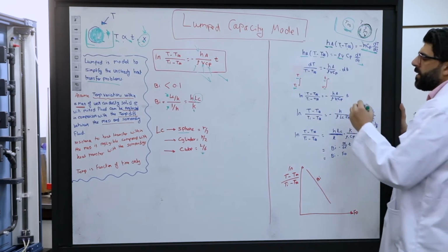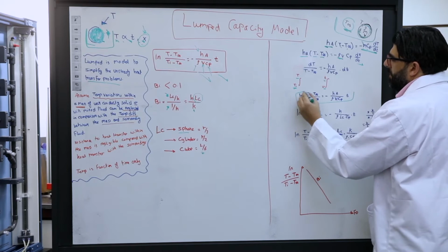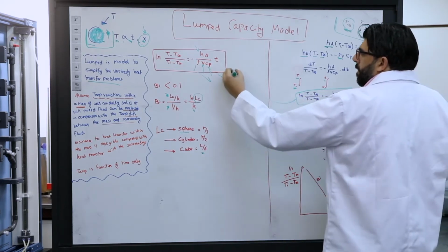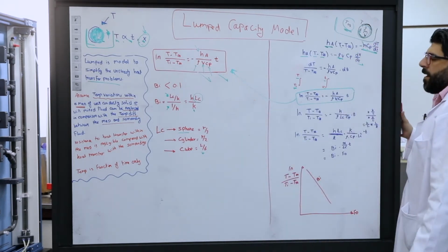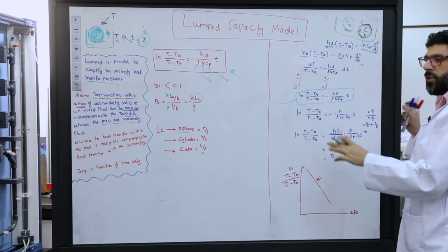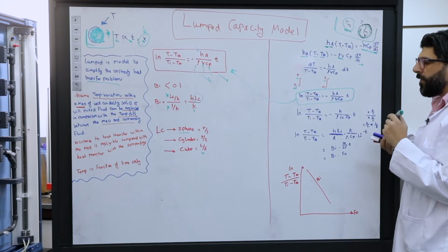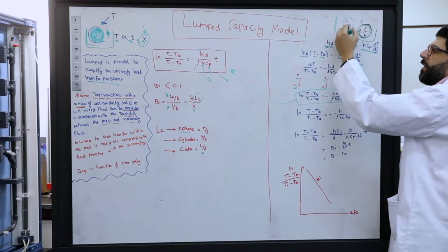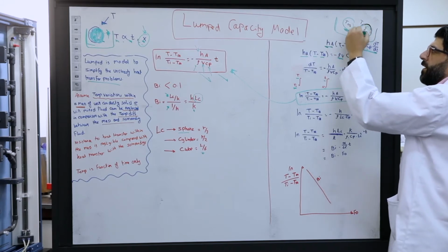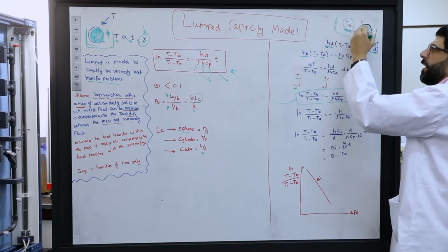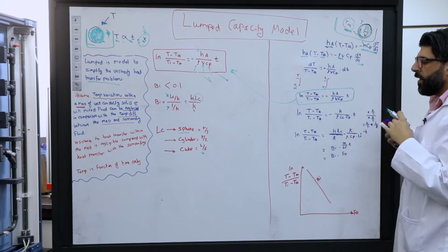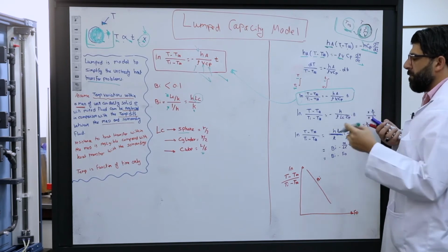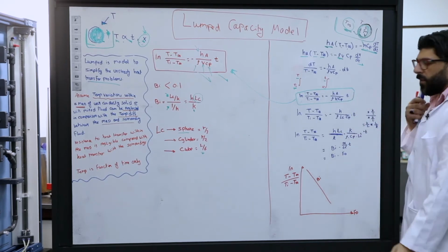So now this equation is the same equation we got earlier. But in this equation we ignored the effect of conduction. We assumed the internal heat transfer is only due to convection, and we neglected conduction. So now let's introduce conduction into this equation, but in a way that keeps the balance of the equation.